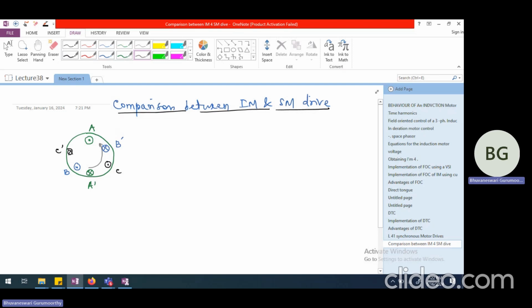So once the revolving magnetic field is set up, if let us say I have the rotor here, let me show the rotor somewhat like this. So this is what is my rotor, two-pole rotor. So if this is the rotor and the shaft is attached somewhere here, so let us say if this is the two-pole rotor and I'm going to have the revolving magnetic field somewhat going around like this. This is probably the North Pole and this is going to be the South Pole at any instant of time, and this is going to rotate at synchronous speed. Then this rotor, which is made up of a piece of iron, or it is going to be made up of some permanent magnet, it is going to be dragged along with these revolving magnetic field. So the basic working is somewhat like this.